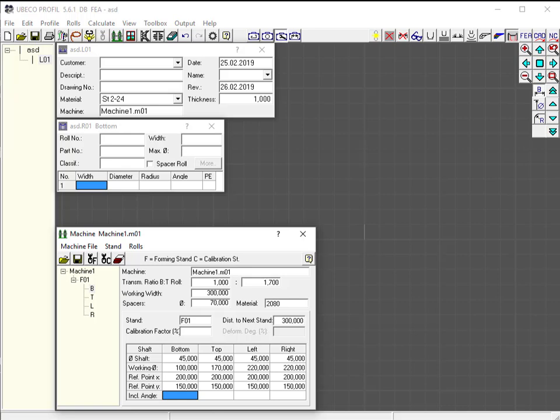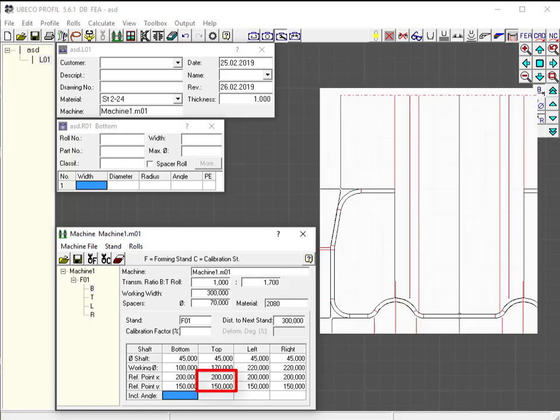If you are bothered by the top roll's reference point position on the lower sheet side, you can leave the X and Y entry fields empty. Then the bottom roll reference point is taken and moved upward by the strip thickness. Then the top roll's working diameter is a real diameter that can be measured.